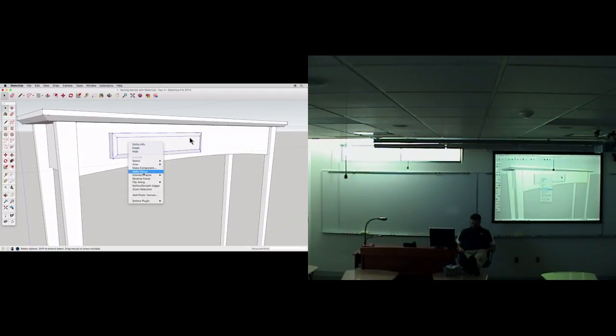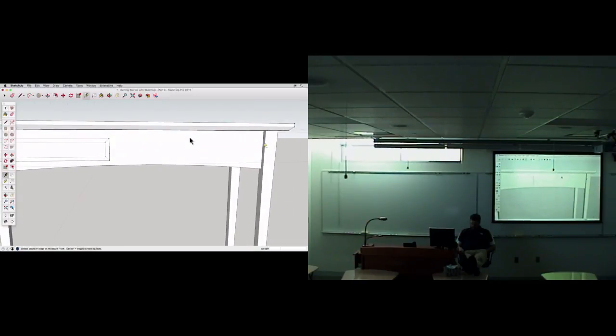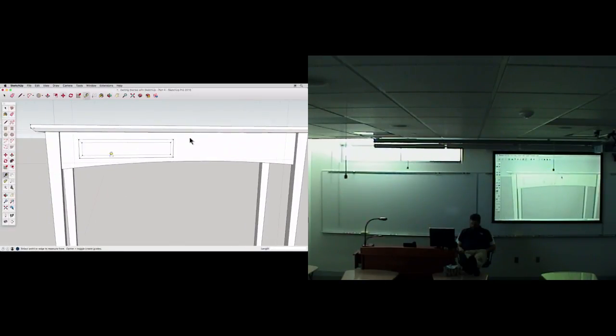We better group the geometry at this point. Triple click to select it all. And if we were going to center the drawer and have only one, we could group it, but I'm going to create 2 drawers, so let's make it a component instead. Now a few guidelines can help with the placement of the drawer front and the copy. Place yours where you think they look best.